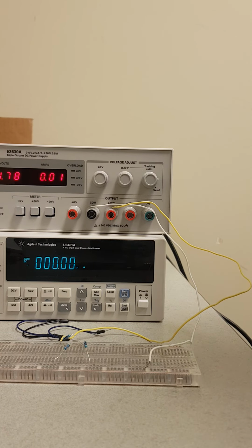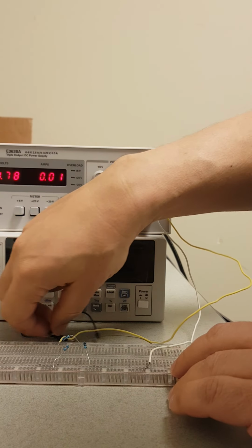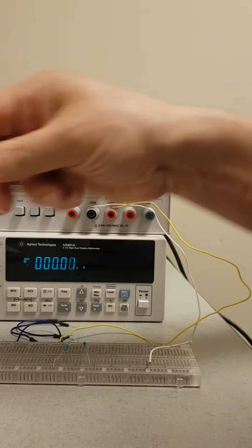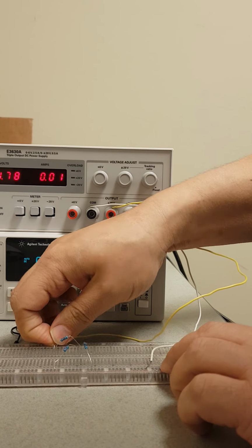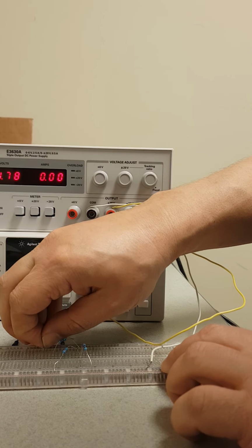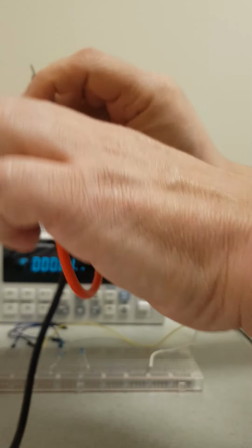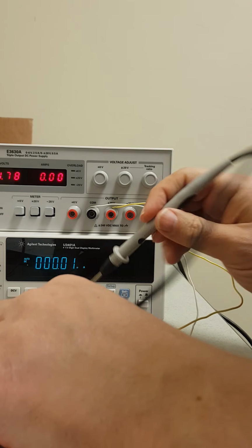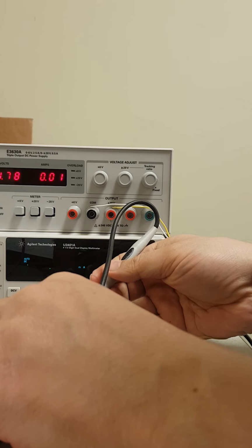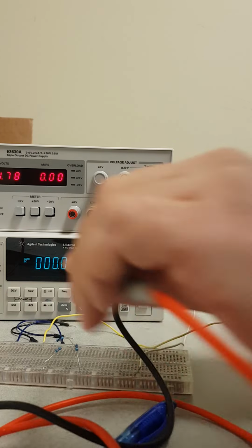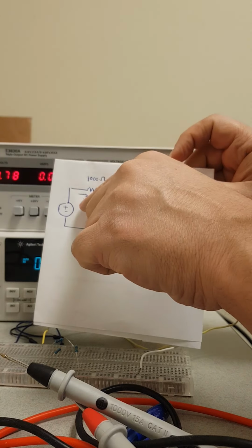As we mentioned before, to measure the current, we need to open the circuit. So let's see the main current, which is the current I. I will need to open the circuit, disconnect the voltage supply from the top resistance, and see how much current that is, because we have to have the ammeter in series with it. If we connect the leads, here this is the positive and here is the negative lead. We see here the current is around 10 milliamps. So the main current I here is 10 milliamps.